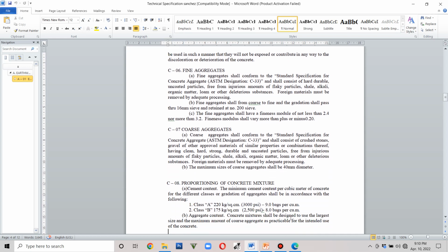In some cases, specified especially in the design mix, when your stirrups are so confined, you need to have a smaller diameter of coarse aggregates. So normally it is 3/4 inch in size or around 20 millimeter minimum, so that we can avoid honeycombing on the pouring of your RC elements.